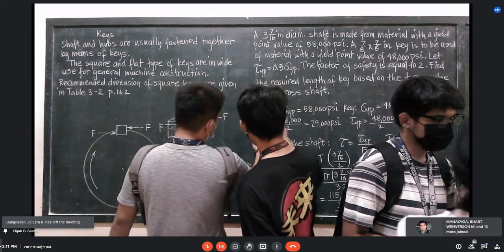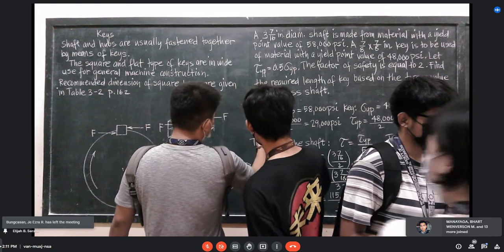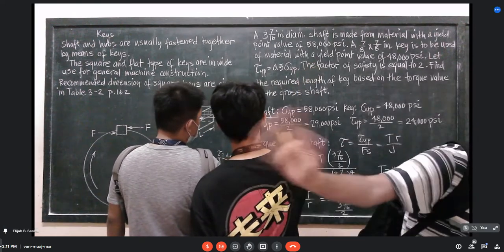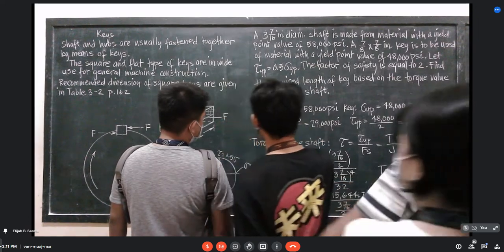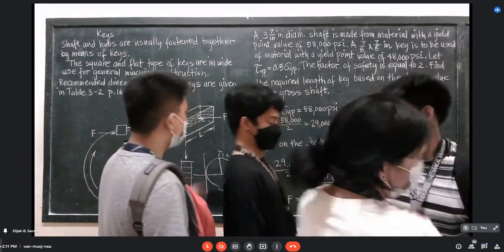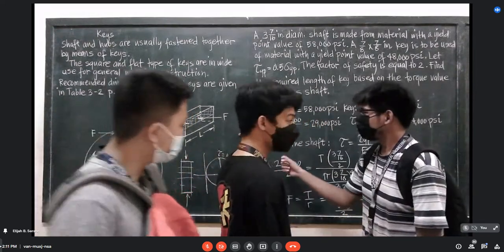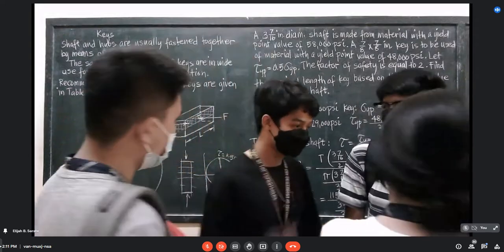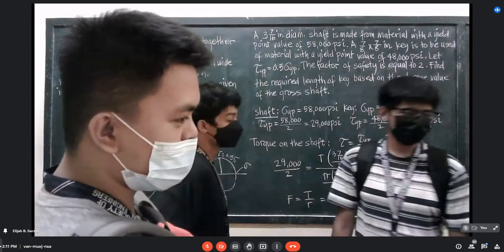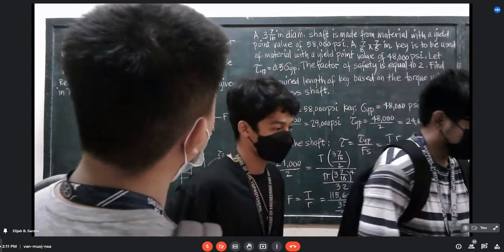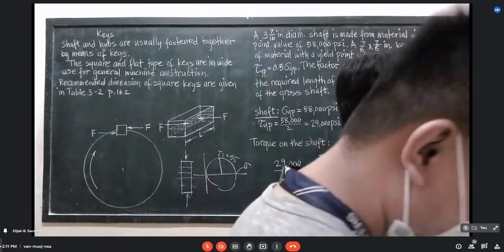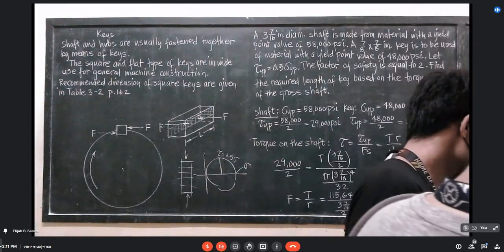What is different? What do you mean different? Sir, the formula for bending stress maximum is equal to Mc over I. Mc top over I. Maximum. Why do you know the maximum is here on top? The moment at the top, then c from the neutral axis towards the top, over I.